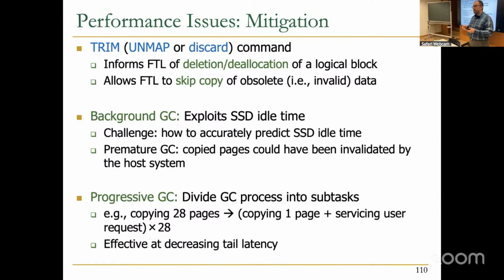In enterprise SSDs, that DRAM is large enough to house the whole mapping table because you want to be fast. But in low-cost SSDs, the DRAM is not large enough, so you cannot house the whole mapping table. So people came up with caching techniques. DFTL is one of the cool techniques, proposed in ASPLOS 2009, if I'm not mistaken, that tries to cache the mapping table. You can also think of prefetching and caching; all these things you can revisit there as well.